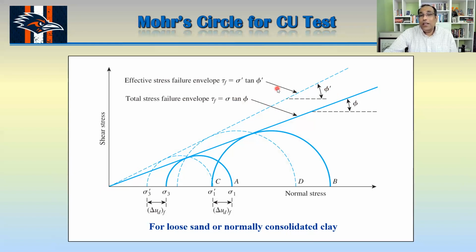If you say no, it didn't dissipate fully, 50% dissipated or 60% dissipated, then basically you can use this line or this value of phi, but basically all the time this is your engineering judgment of how this one is happening, okay?